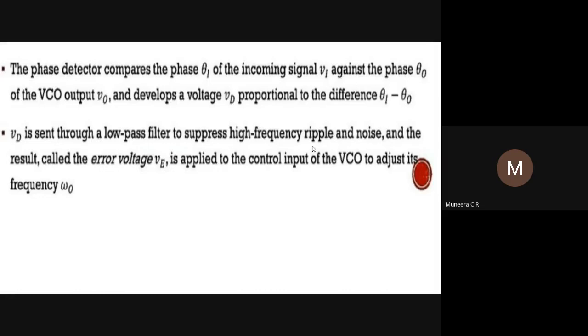So the phase detector compares the phase of the incoming signal against the phase theta 0 and develops a voltage proportional to the difference between theta I and theta 0.